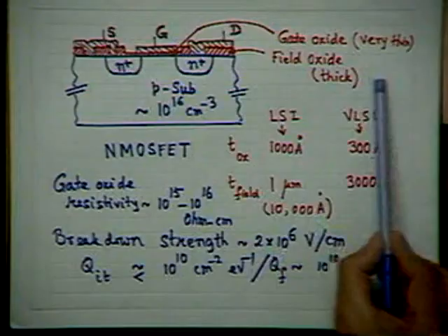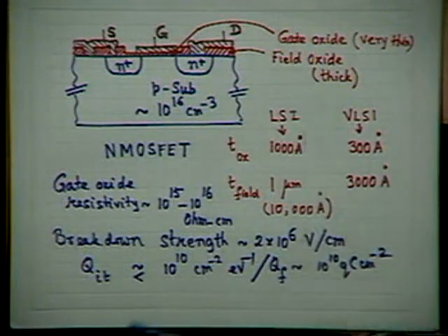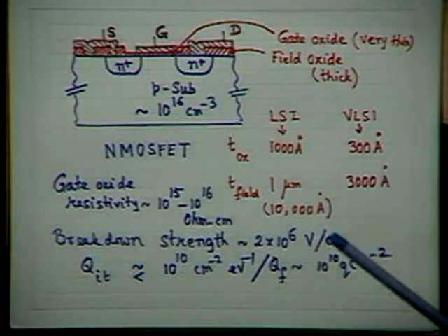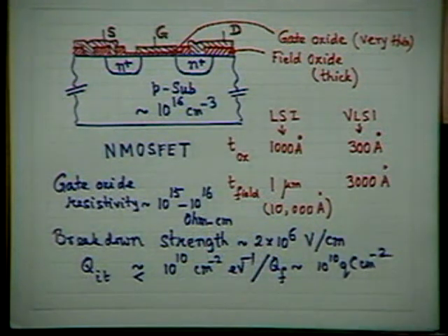Again, I am in a problem because the resistors cannot float, cannot be just done like this. I have to have some isolation. Either you have an N plus region into which you may have a P, and that P may behave as a resistor. And because you need extra isolation, you are going to sacrifice a lot of space. Your packing density is going to suffer, so therefore it is not a good idea to have normal linear resistors in a MOS circuit.